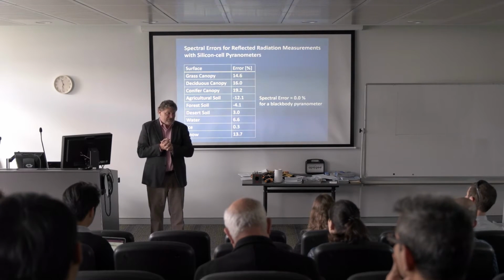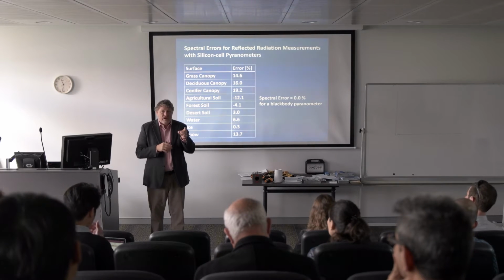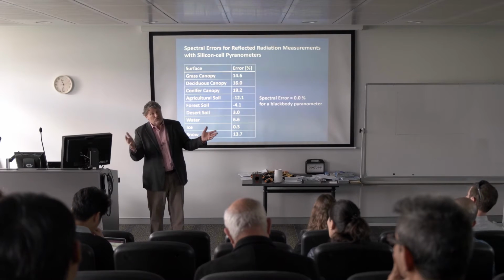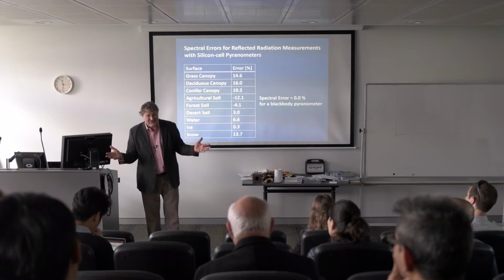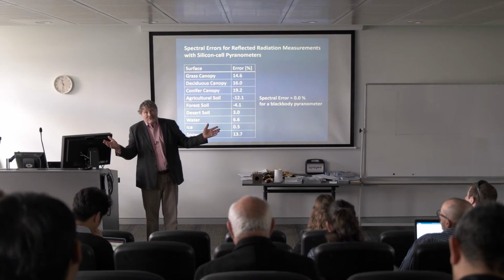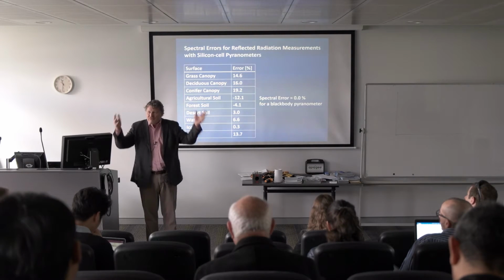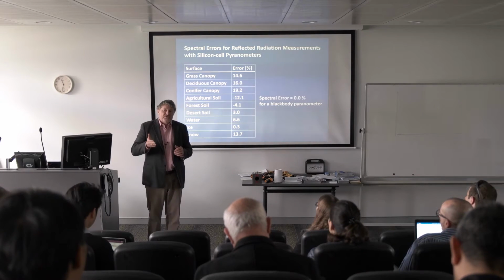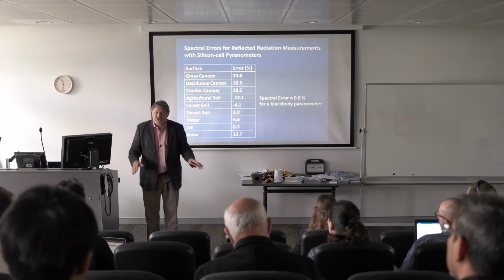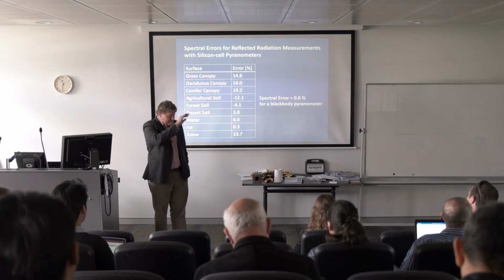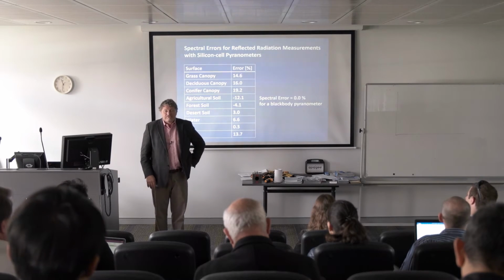Occlusion of the sensor, of the dome, is a problem. Some sensors that are flat trap debris, they trap water, they trap dew. That's an error. And of course you can clean the sensors, but how many of us do? We don't. And now they read 10% low. Maybe until you get a windstorm, or not a windstorm, a rainstorm, and it flushes the sensor clean. Sensors that have a dome top help a lot. The water is self-cleaning and the water tends to run off. So those dome tops help keep the sensor clean.